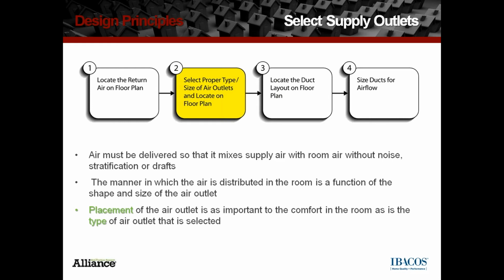Selecting the supply outlets is critical to the performance. Like we said probably 4 or 5 times already, the air has to be delivered in a way that it will mix with the room air. The manner in which that air is distributed really depends on the outlet that you've selected, and the placement of that outlet is just as important as the type, where you're going to put it so you get good performance out of it.